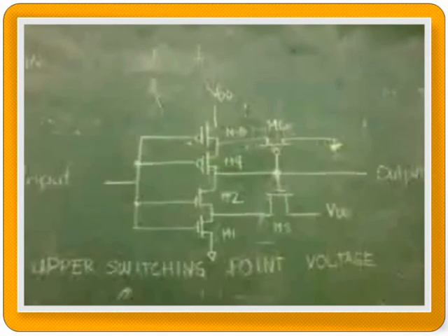A general design rule for selecting the size of M2, that is beta sub 2, is to require that beta sub 2 is 1 over beta sub 3, which is equal to W sub 1 times L sub 3 all over W sub 3 L sub 1, which is equal to the quantity 1 minus 0.55 all over 0.55 minus 0.25 quantity squared. This will give us an answer of 2.25.